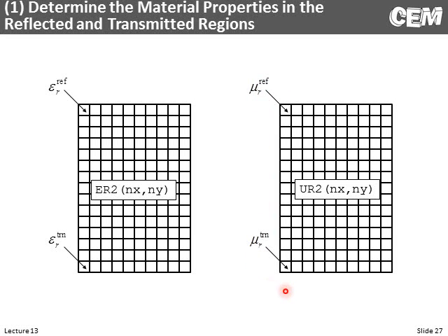Remember, the way we're formulating this with a plane wave source and the way we're calculating transmitted and reflected power requires that the reflection and transmission regions are homogeneous. So our device cannot be here. We need to have all the same values in the horizontal direction. We can have all kinds of craziness in the middle, but at the edges, where we're calculating transmission and reflection and injecting the source, it must be homogeneous. Now that isn't an absolute requirement, but we would have to do our sources and power calculations differently.